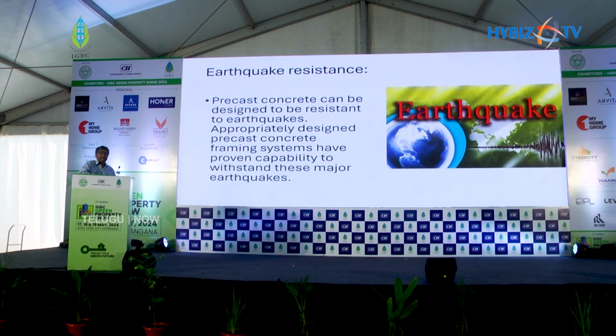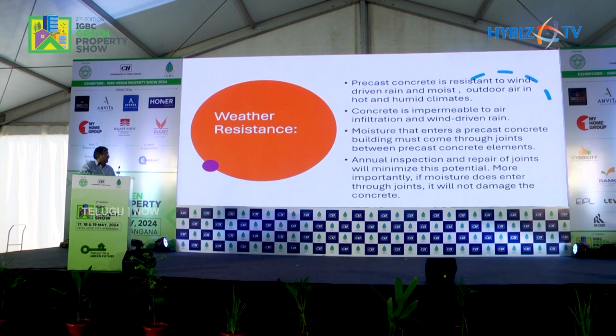If the total building is made of concrete walls, then the building hardly deflects due to earthquake. A 30-story building hardly deflects by 30 to 40 mm, as we have seen in the design for Zone 3 or even Zone 4, when the walls are built with concrete. That shows the strength of concrete.